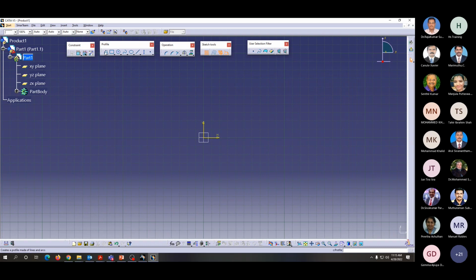It also depends on your sketch, depends on your model, how you are going to create everything. So first, I'm just going with this profile. How do we have to start? First, I'm just clicking on that. After I click, you can see it has been highlighted with orange color. This is our coordinate axis, which shows this is Y and Z, because we have selected the YZ plane. Here you can see this is the Y direction, this is the Z direction.